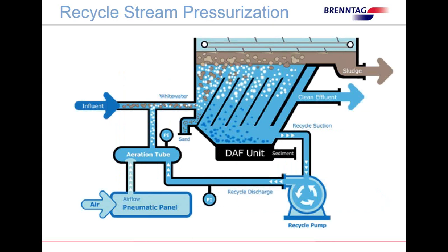I put this picture in just basically to show that some of the newer designs, we're starting to see them incorporate the use of parallel plates, very similar to the lamellas, which makes for a better separation through the unit, better solids removal. So these are some of the new designs that we're starting to see, the use of parallel plates within a DAF unit.